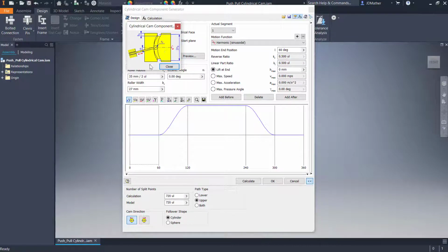So we're going to have to be clever with this, where we're going to move this bottom of the slot up and the top of the slot down, because the bottom of this roller, we need for a roller up here to follow this face up here, and then a top of a roller here to follow this face down here. So we're going to have 2 rollers here instead of just 1 roller. And let's look at how to set this up then.